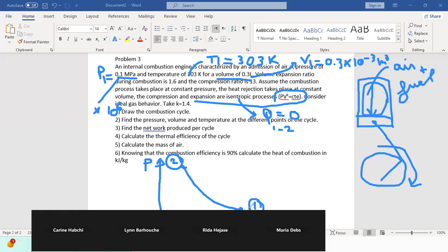After this, when we compress our fluid, it will reach high values of pressure and temperature, and then it will be ready for when we inject, and in case it's a diesel generator, we inject diesel. Once we start injection, after a certain time, we have auto-inflammation of our mixture, and we have the combustion process. The way we introduce the fuel, in case you have a diesel system, depending on the law of injection you use, this will affect the combustion process.